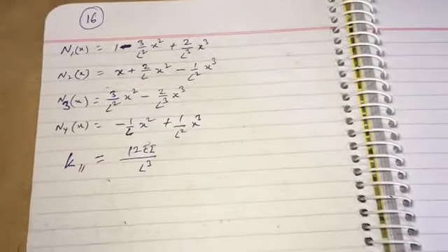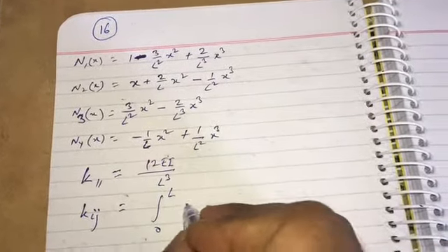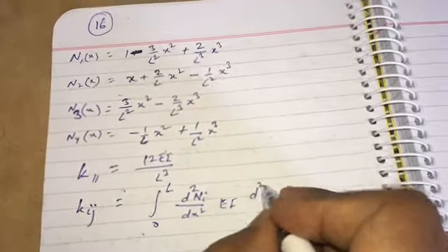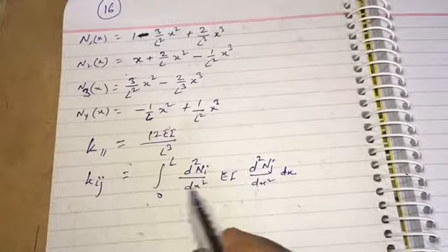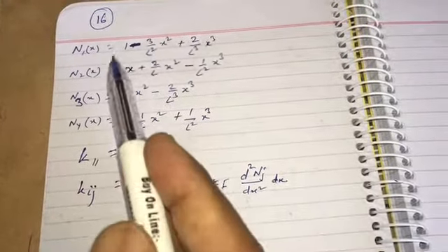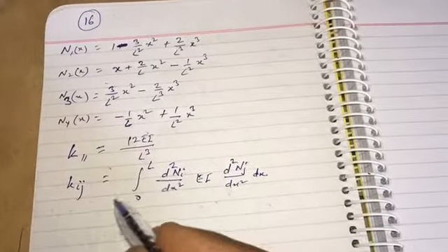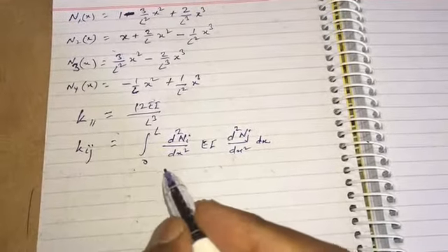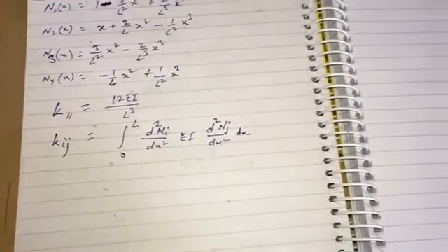the K12 component. As I said earlier, you can just use this equation, Kij equals the integral from 0 to L of d square Ni dx square, EI, d square Nj dx square, dx. If you use this equation and the shape functions, you can integrate it and find it very easily. However, you don't have to evaluate all of them. A few things will be known automatically, and that's what I'm going to show,